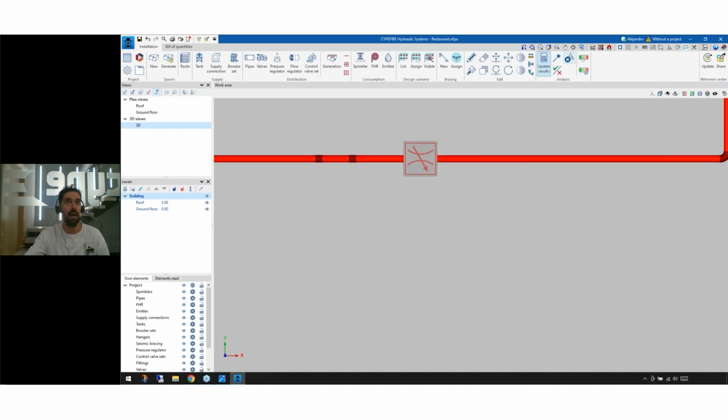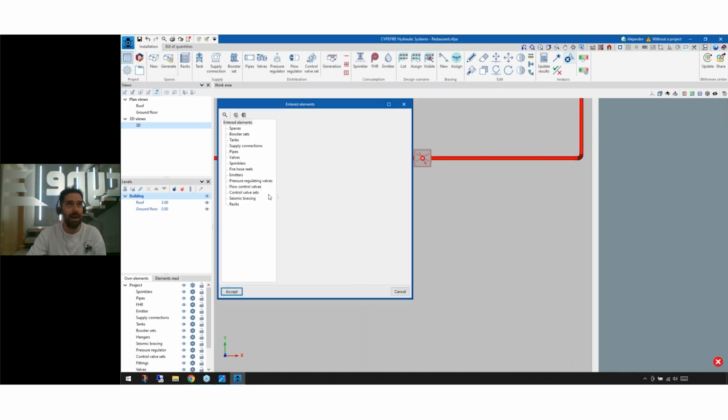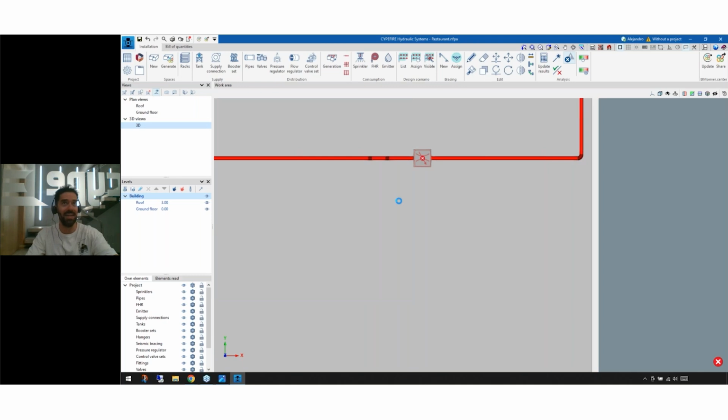So we have also added a message here that tells you that you have to reverse the inlet and outlet nodes. You only have to use maybe the rotate group or the element. As I did it is really complex because it's not the best way, the easiest way to do it. So you will have to flip it with this edit tool here. And this will be everything.